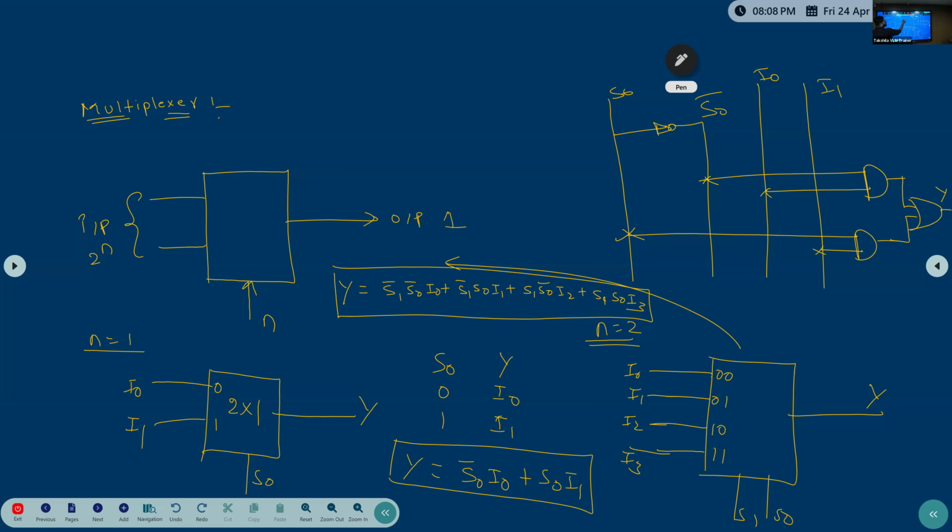This is the spare cell group here, and I want one AND gate functionality here. Somewhere we'll have another one, but going from here to there and coming back will create a timing problem for me. So here only one mux is there, and I need to implement AND functionality. They will ask to implement AND functionality using a 2:1 mux. Okay, first I will go with the inverter, then you will understand. Then we'll go with AND gate and OR gates. So, inverter or NOT gate.